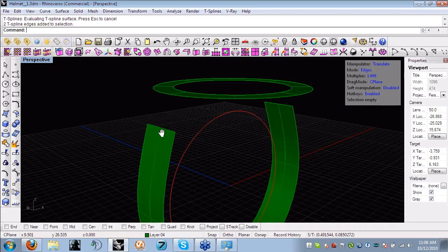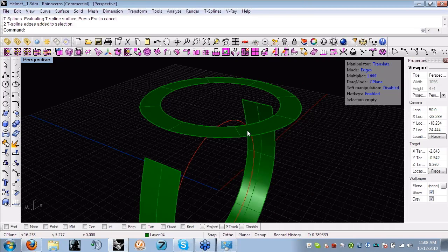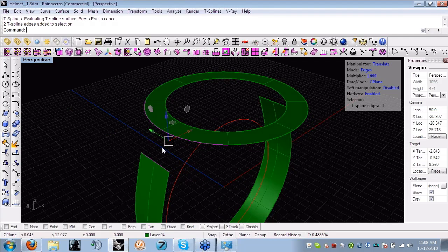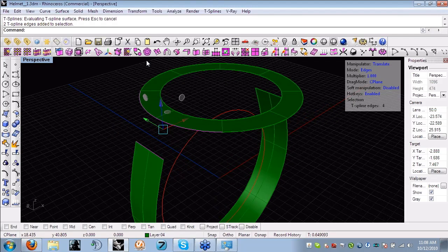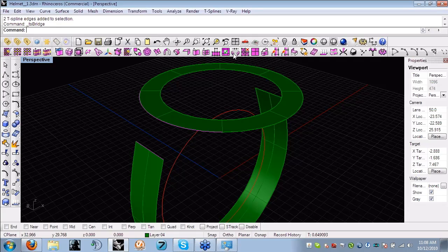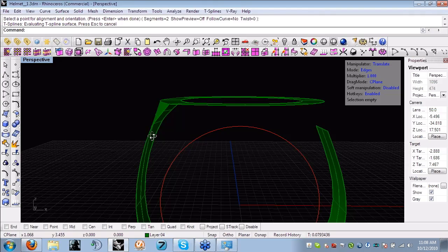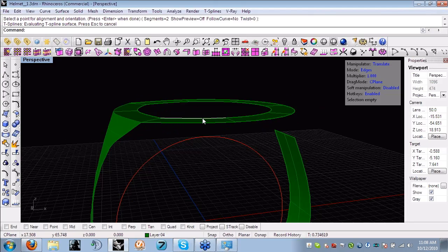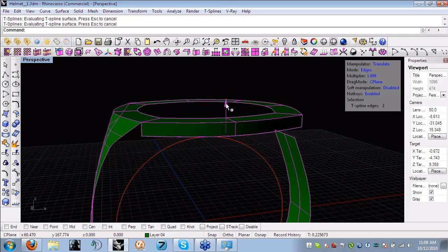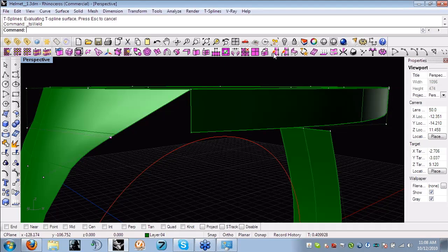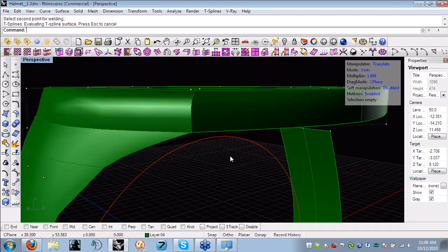But I think doing it this way, I like doing it with the primitives because I can visually see how many faces I'm going to get so that I know that face lines all match up. So for when I do things like bridge, I can get them all together nice and easily. So I'll bridge that. And so I pretty much go along and just bridge, and then this is straight out of Juan's video. No secrets there. And then, you know, weld U to U like that.